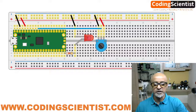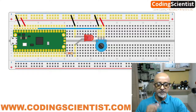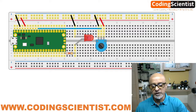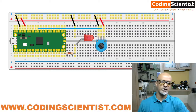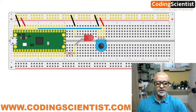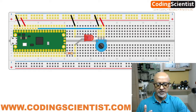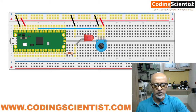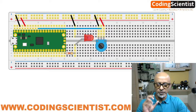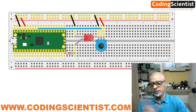The circuit is almost the same as the previous drawing, except that you need to pull out your push button from the previous lesson and replace that with your potentiometer. If you don't have a potentiometer, guys, it's available anywhere on Amazon or online. It's just a few cents, probably about 30-40 rupees, Indian rupees. So go ahead and pick it up. A 10k potentiometer, 10 kilo ohms, is more than sufficient, and do the wiring according to this drawing. You can pause the video, take a look at the drawing, or you can copy it, download it, keep it with you and build it.